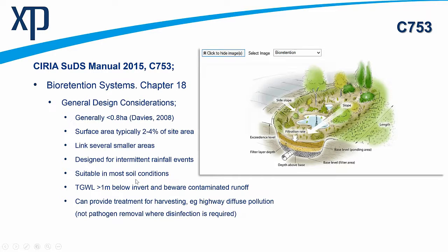And they are suitable for most soil conditions. So we can put them into clay soils and pipe away. We could infiltrate into the ground if we're in areas of alluvial deposit. The very steep sites, you may have issues. It's still kind of feasible, but you may have to offset the cost of putting something in that, as I mentioned, I'd like to have that in virtually horizontally rather than with a great slope. I don't want this scouring out. There have been some bad experiences in Australia. They've used these an awful lot in Australia, and there's been both good and bad experience there. So we've learned a lot from their experiences over there.